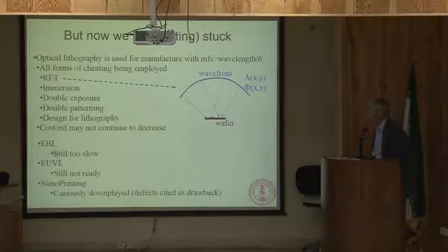But then you might say, well, why not go to electron beam lithography? It has finer, much finer resolution. You can resolve 1/10 of a nanometer in a good transmission electron microscope. And so this is an area which I've been heavily involved in. And you might say, a fair chunk of my career was proving that this wouldn't work. And the reason is that electrons, as you may know, repel one another, and if you start to push enough electrons through to expose the resist in an economically fast enough manner, the repulsion, the space charge effects, will introduce aberrations and will defeat your purpose of trying to get high resolution. I will show, I think, one slide of the EBL, because there isn't a way that you might get around that. This is where the industry has placed all their bets.